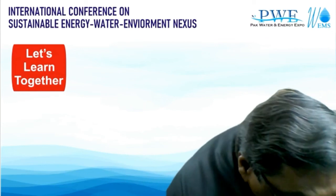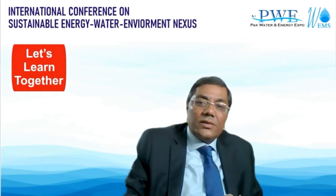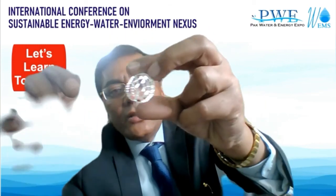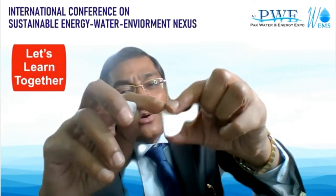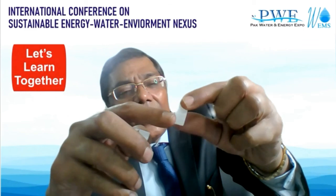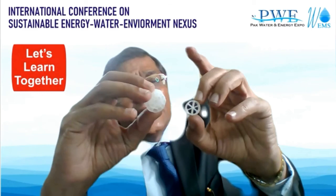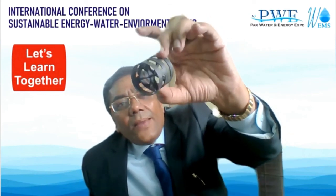MBBR, any media there, perhaps I will have something to show you. These are the media, if you can see me, these are the media balls. I don't know if you can see these. These are the balls which are used in the MBBR, and here the attached growth occurs. Normally for high pollution load, these filling media are there. And you can see this other one, the bigger one, these types are available.